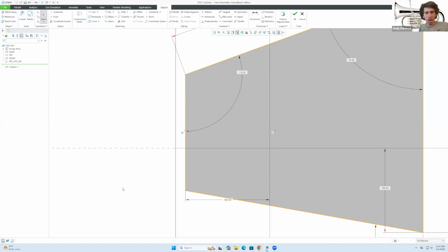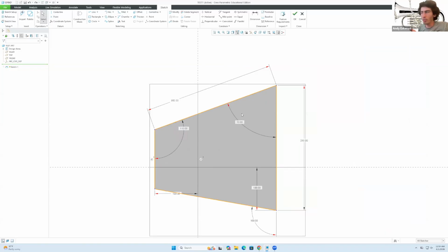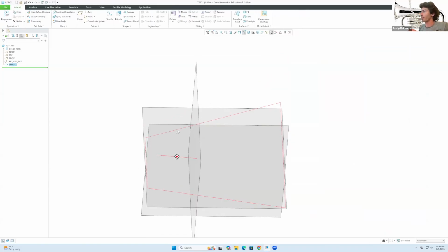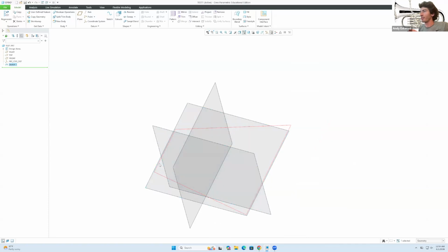Okay, you have your sketch in here. You're happy with it. You click here on okay. So now I'm just going to rotate our sketch, which now appears there as Sketch 1. By the way, this area of Creo is called the feature tree. It's a super useful place because everything that we draw is going to keep popping up in there.